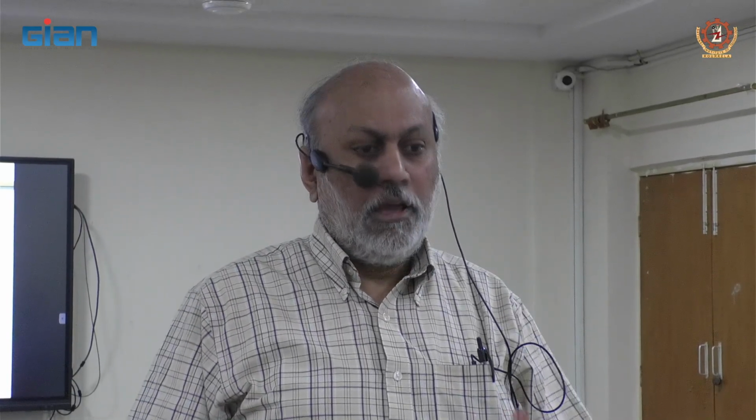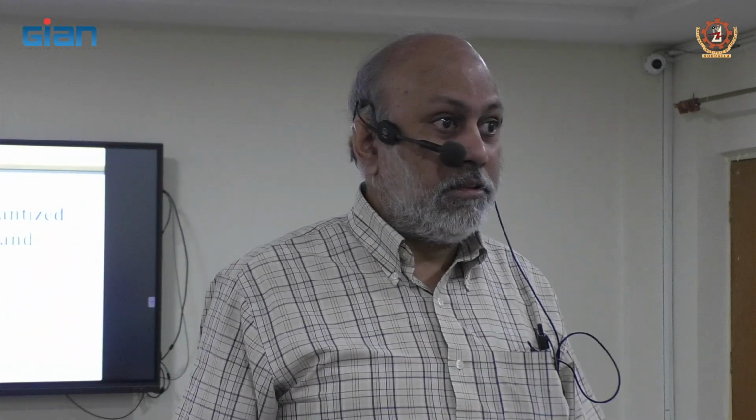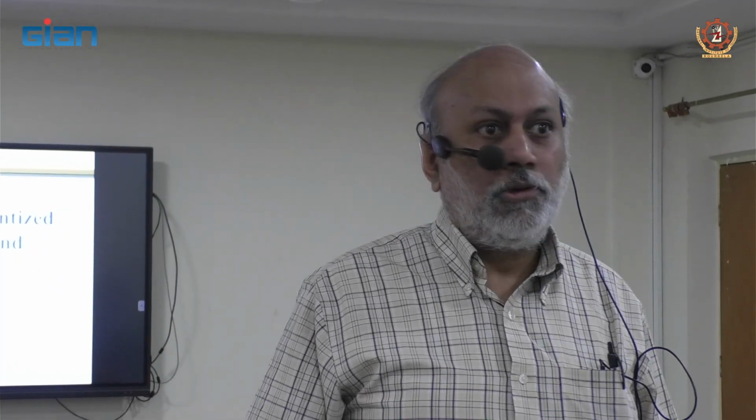Okay, so that would be a design issue. Her question is that if you are dealing with an NCS system, we provided all those values like the delay and so forth. So how do you determine that? When you are about to design an NCS system, the first thing you need to know is what type of network you're going to have. Is it a wired network or a wireless network? A lot of us prefer wireless, but there are challenges, because wireless bandwidth is a lot less than a wired system. So you have to deal with that.